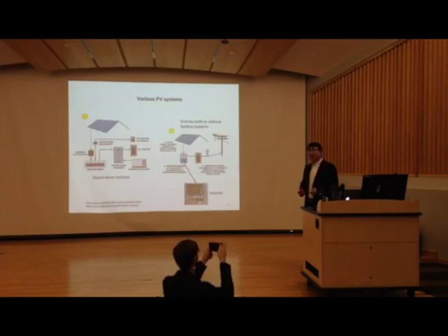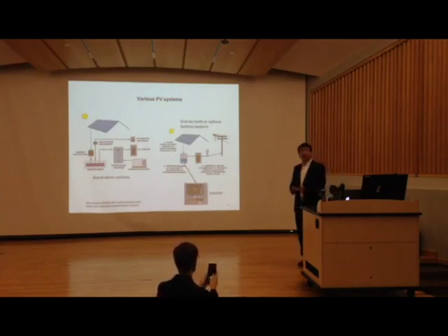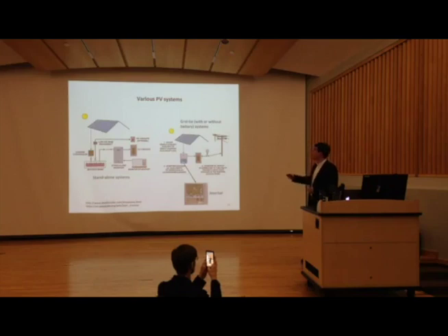And if you have that, it's still a DC voltage. Maybe it's quite high, up to, say, 100 volts, but still DC. How to get from DC to AC? You have to go through a whole stage. So now I'm going to show you two types of PV systems. Typically in Alberta, we have this type of PV system. The first one is called the standalone system.